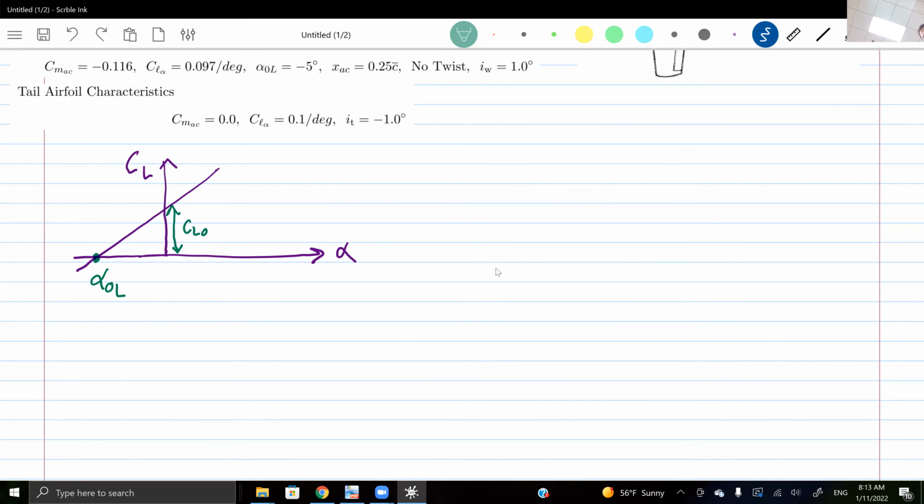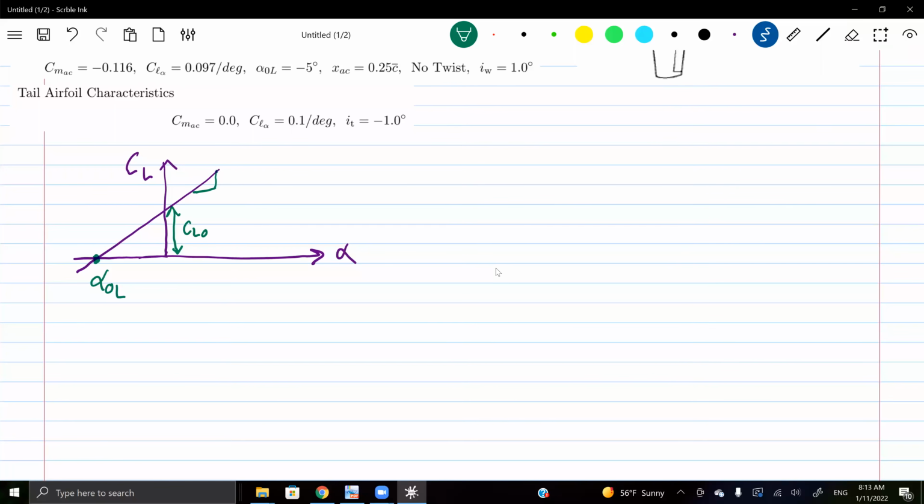All right. And the slope of that curve is what? What do we call the slope? Anyone can guess? CL alpha. Exactly. This is the CL alpha. So the slope is the CL alpha, the slope of the lift curve, which is 2 pi for a 2-dimensional airfoil, and for a 3-dimensional wing, we know how to get it, and we're gonna do some training on it now. So from this geometry, can you give me CL naught in terms of the rest?